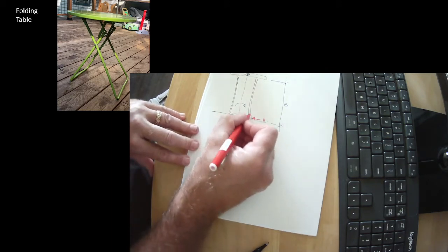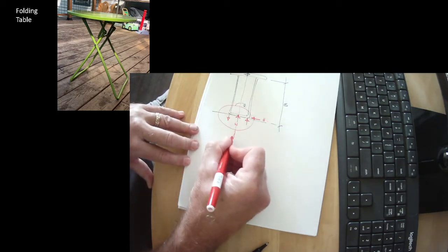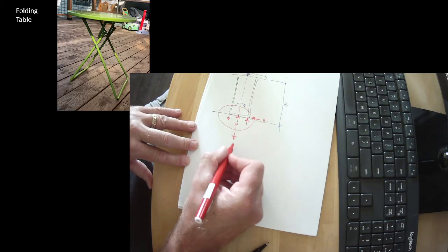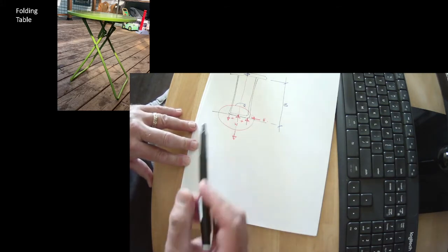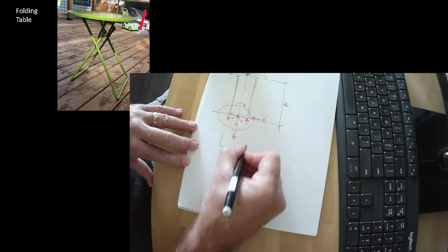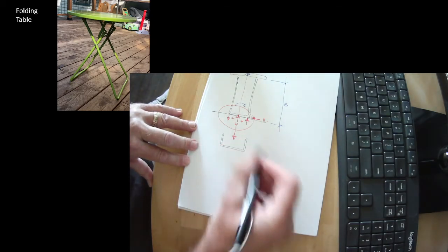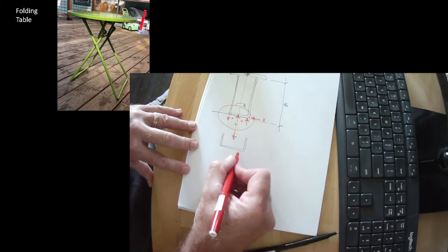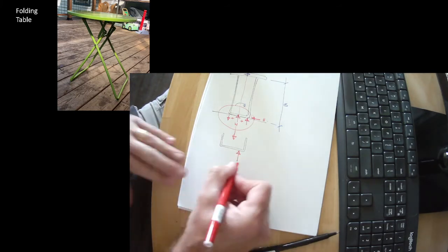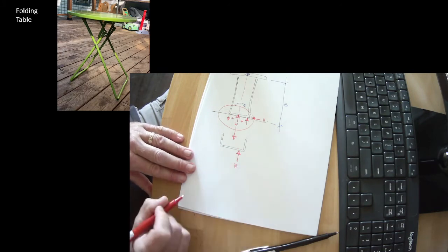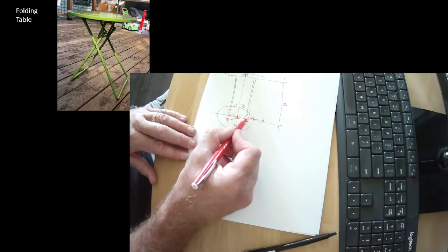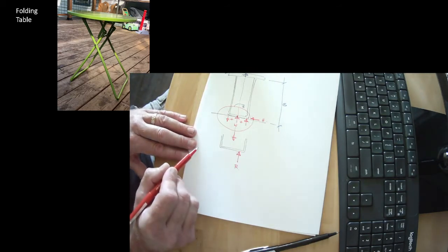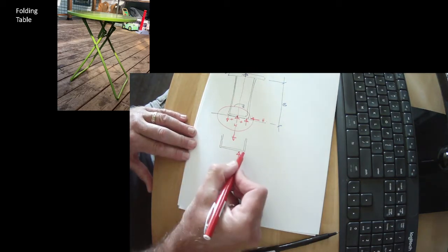Okay, so let's look at what this does to us. Let's find the resultant of those three things, this plus this plus this. Redraw the bottom. What we wind up with is a resultant out here somewhere. That is our resultant. But it's not point loads. We don't just bear on discrete points. We bear continuously along the surface.